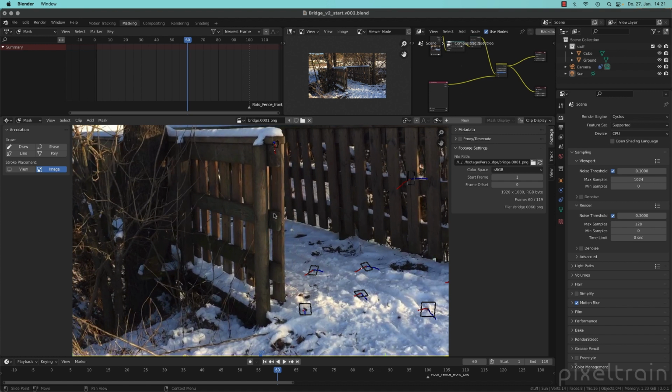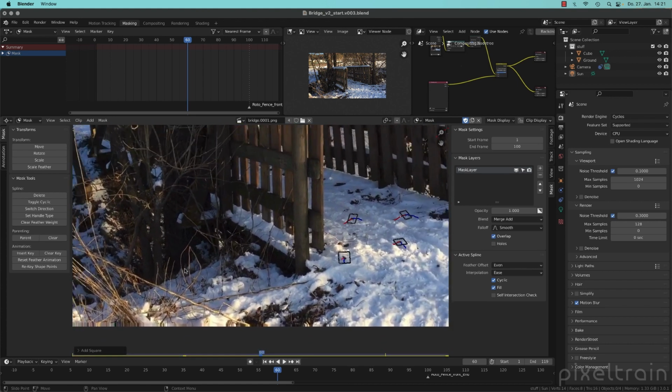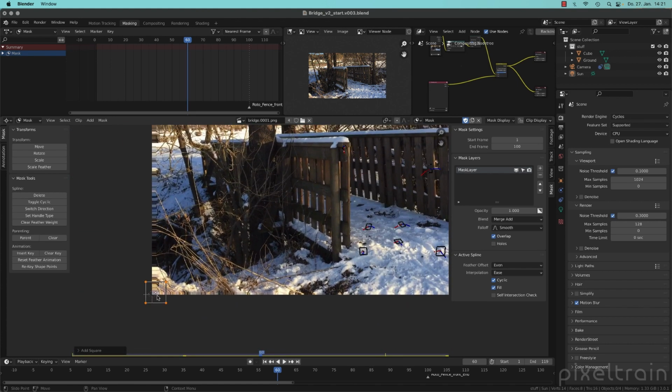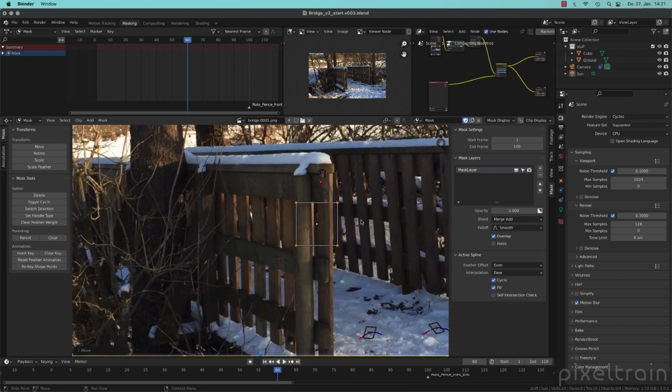I start my first part of the mask with a square, and like I've said, at the moment we don't have a mask at all. That's the reason why we don't see anything here. If you click start, you get it here, or you can add a shape, you get a new mask, and now the mask normally is at the left corner. So that's the mask. If you want to select all the points, you can press the A key, the G key for moving around this area. Everything which works in Blender works also here. It's absolutely the same thing. Okay, these are 4 points like in splines.